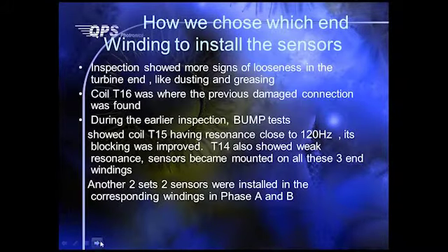So in this case, we did not independently choose the location where we put the sensor. We consulted the customer, AEP, and were guided by what they wanted to do. Clearly, since earlier inspection showed that they had a problem of looseness in the turbine end, and they saw a lot of dusting and damage from copper debris, we decided to help them put a lot of sensors on the concerned area.